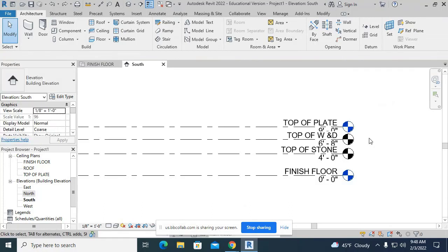You need to identify what scale you're printing to. That's important. Now, residential project, most of the time, 1/4 inch scale, 1/4, good job. So your exterior elevations are also 1/4 of an inch. What's my scale here? Is that correct? No. So don't spend all this time adjusting it when it's going to change.